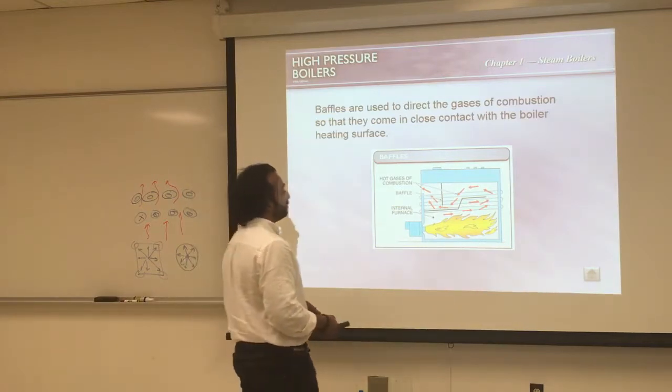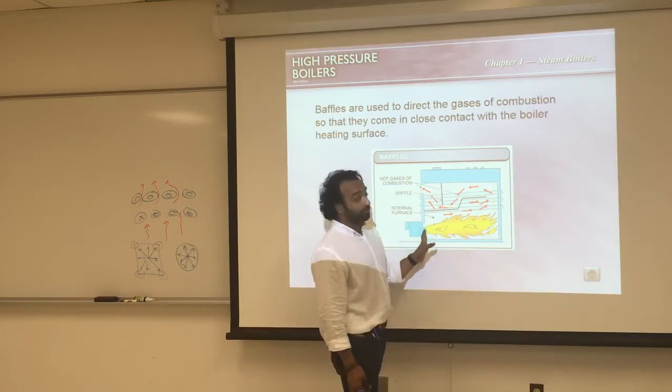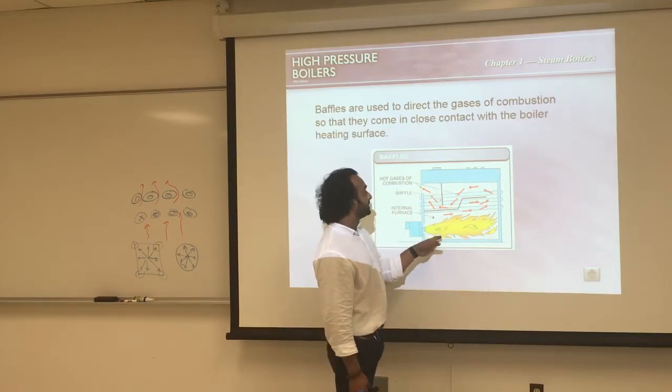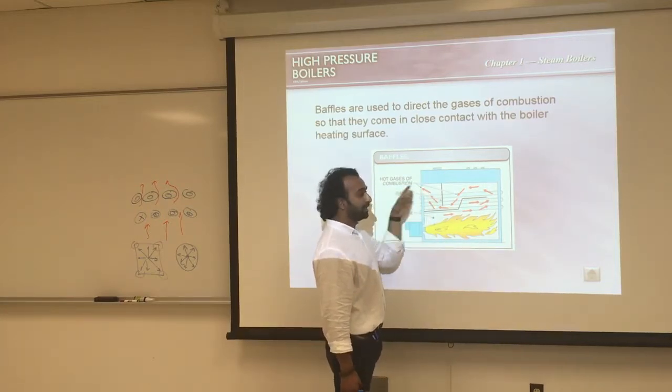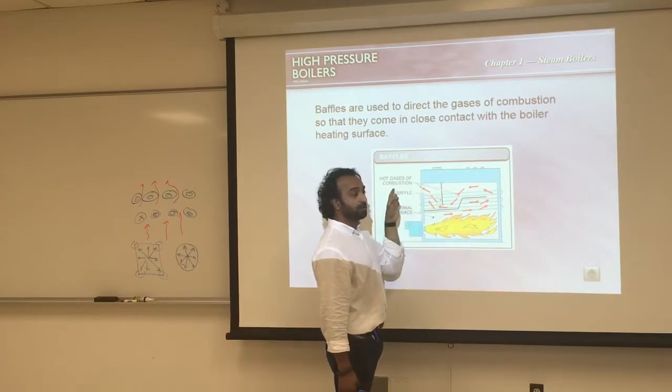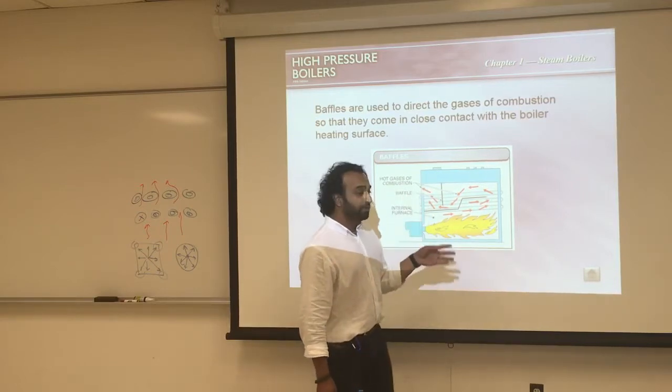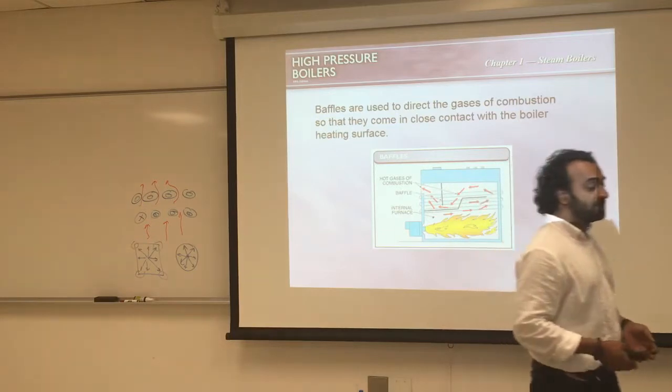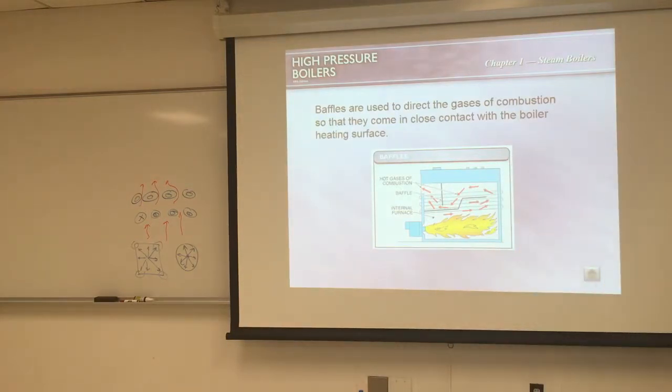And again, we have to always be very careful. We have a design temperature for the combustion air and a design temperature for the outlet of the air, because we don't want it to be too cold. At some point, if it gets too cold, it will start to condense, and most of the condensate will be very, very acidic. We'll talk about that later on.